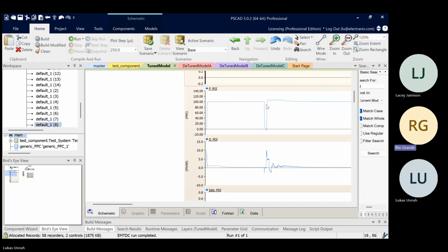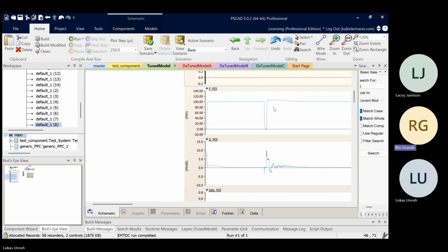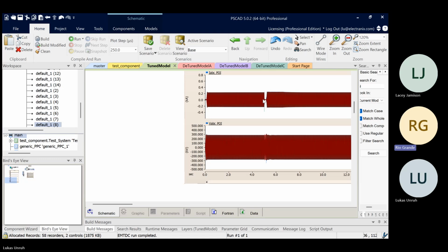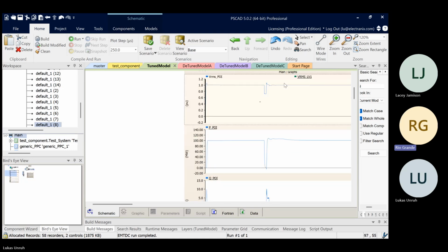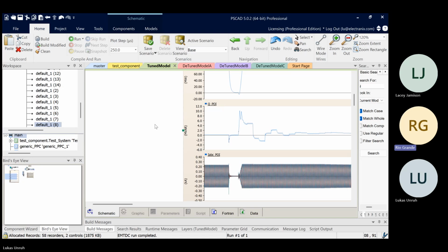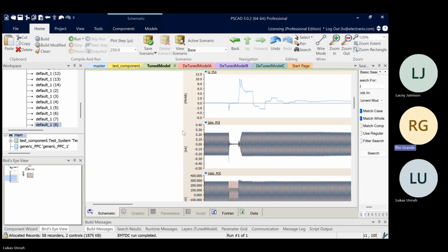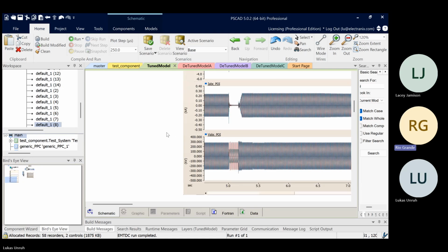And it is riding through and behaving a little bit, you know, if you look at the current, the basic current has gone effectively to 0 on this one. So it has basically gone into full momentary cessation. So that's not great. Probably we would flag this one and say you're not providing any fault current for this test. That's something that we would probably call out for this one.